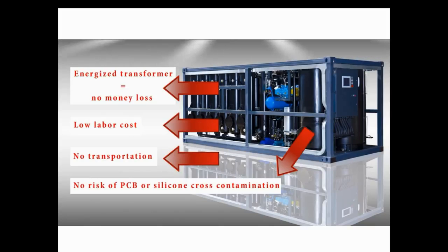But most important is to remember that when you change oil, 15% of old oil stays in the transformer windings. So consider, we put in new oil, 10–15% of old oil is still in the windings, and in 1 month's time an equilibrium happens in the transformer.